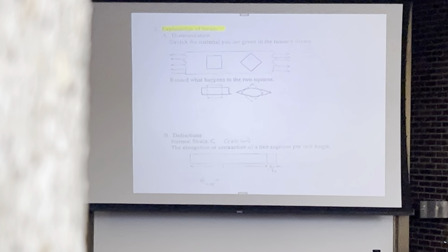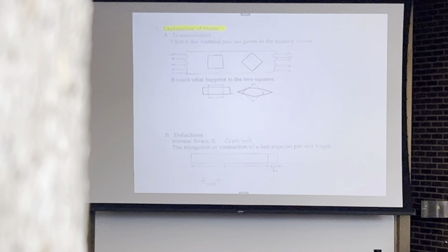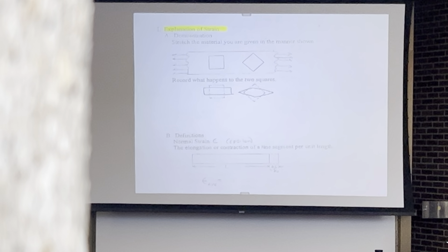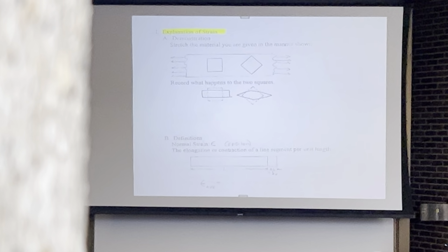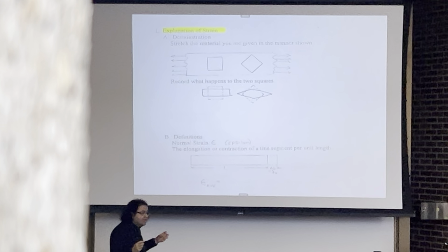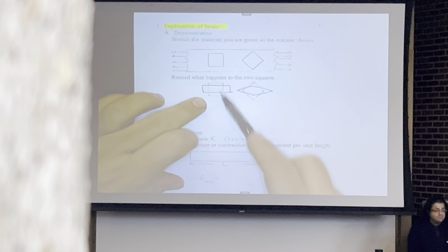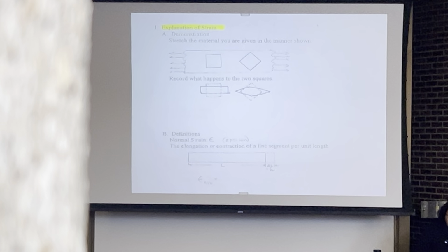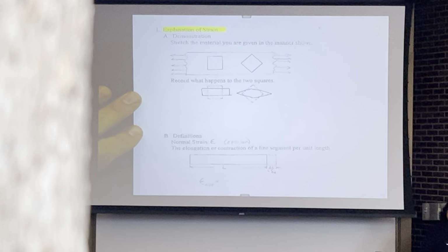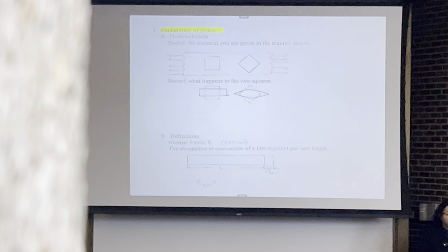As you can see, on the left square, we see changing the length in the longitudinal direction and changing the length in the transverse direction. And by direction, I mean direction of loading. So the length of the element is increased in the longitudinal direction, and decreased in the transverse direction, or in the direction transverse to the axial load. But this second element does not change length, the angles are changing.